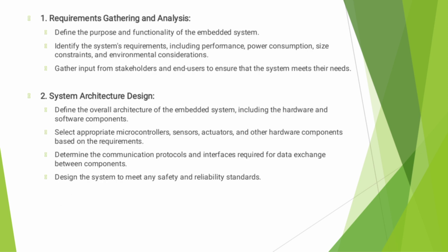Then requirements gathering and analysis. Define the purpose and functionality of the embedded system. Identify the system requirements including performance, power consumption, size constraints and environmental considerations. Gather input from stakeholders and end users to ensure that the system meets their needs.